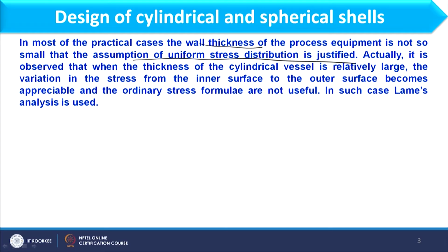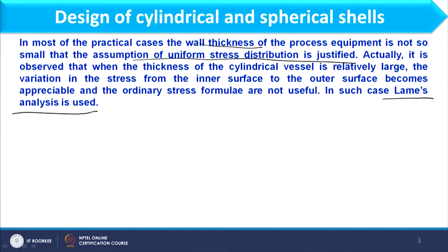However, when I am having a thick vessel where thickness is significant, in that case radial stress also matters along with hoop stress as well as longitudinal stress. So when I am having a thick walled vessel, whatever expressions we have derived for membrane stresses will not be applicable. So to design the thick walled vessel we will use a different analysis, and that analysis is known as Lame's analysis, as it is mentioned over here.